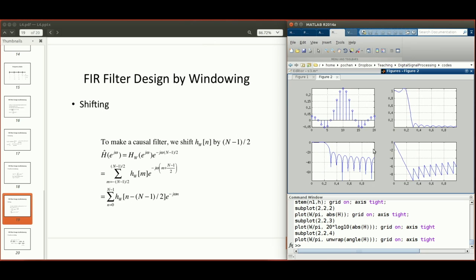So that's the time domain impulse response. First of all, it's a finite impulse response, a FIR, because the duration is finite. And it's actually a linear phase causal filter, because the entire sinc function has been shifted. The negative time part has zero amplitudes, so it's a causal filter, and it has been shifted by a factor of 10. So you have a linear phase for it.